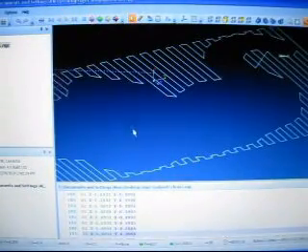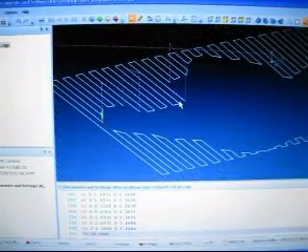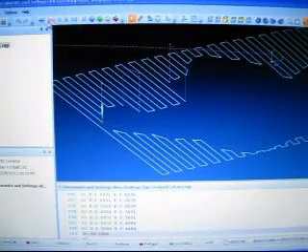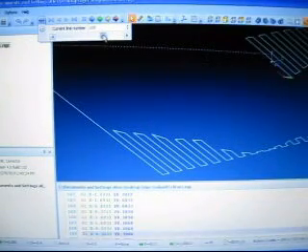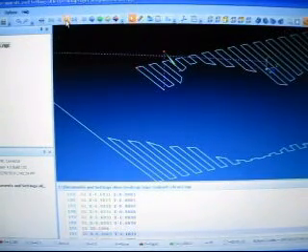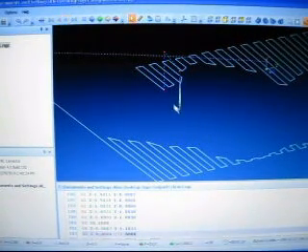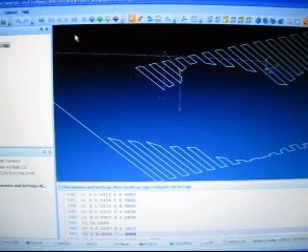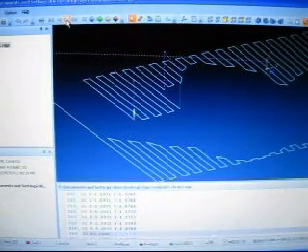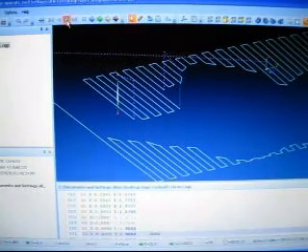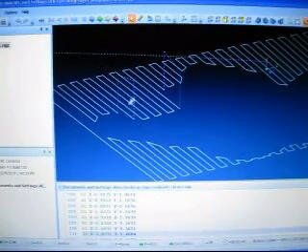I'll just let it feed. And okay, so right here I'm noticing a couple of extra rapids. Let me back this up to these two rapids in question. Okay, that right there. That rapid motion I don't want, but I don't want it to cut away from my part. And that's just going to keep feeding in the proper direction. And then it does another rapid there again. I want to check that. Okay, I just don't want it coming out, down, and plunging into the part.